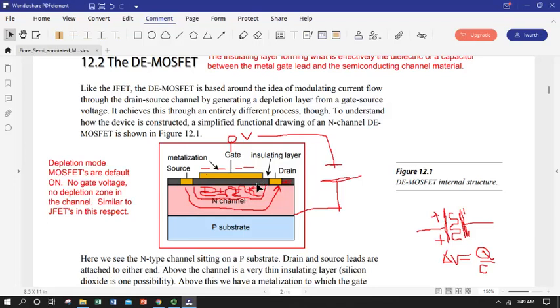And in fact, you can ruin a device just by taking it out of its plastic container if that plastic doesn't have a charge draining polar component to it, like the pink plastic. So electrostatic discharge sensitive devices, you may have heard of them, this is it. And it's this insulating layer that makes it electrostatically sensitive. So that is a very, very important practical word of caution when dealing with these components.